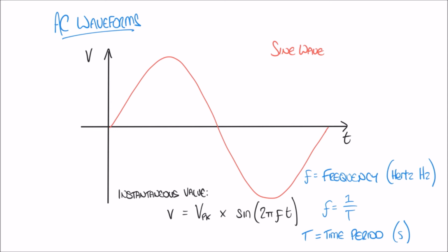And we said that one full waveform is what we see here on the screen. We start at the center point, up and down and back to the start again as one full waveform. So the time that takes, measured on the x-axis here, is our time period. I could also rearrange this formula, f equals 1/T, into the form T equals 1/f. So if I don't know the time period, I can calculate it by dividing 1 by the frequency.